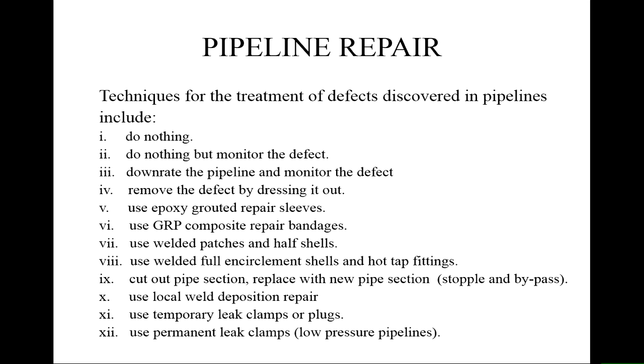What else? Temporary leak clamps or plugs, and finally permanent leak clamps. The temporary ones are generally used for high pressure pipelines and for low pressure, but they can be left permanently once installed. Okay, so I'm going to stop here.